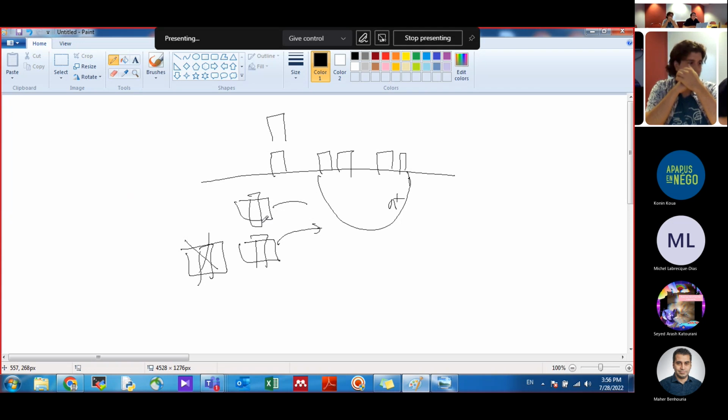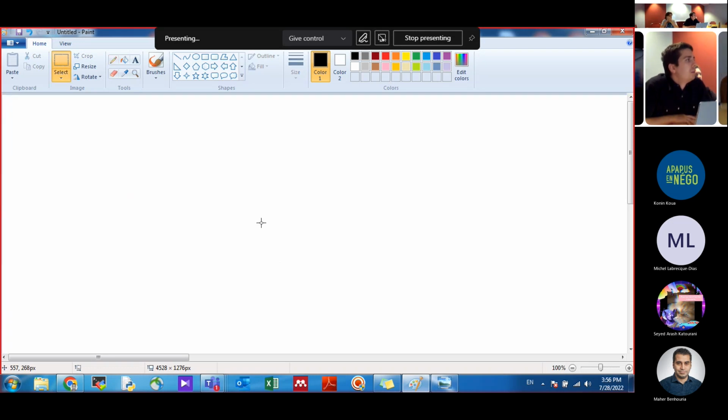In your experience, how much dummy layers do you use? Never use dummies. Always do not care about that because it works. It depends on the technique. Let's say 1 micrometer away. This is the edge of the active region.